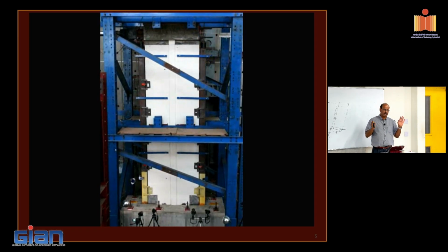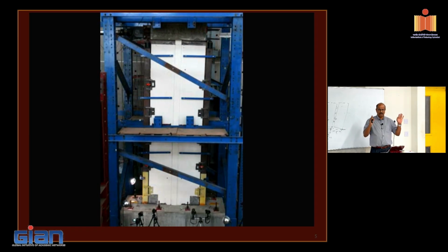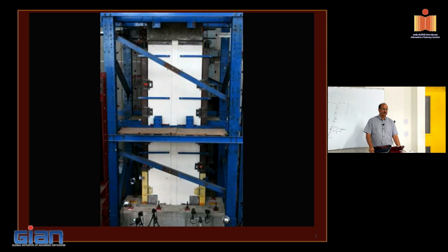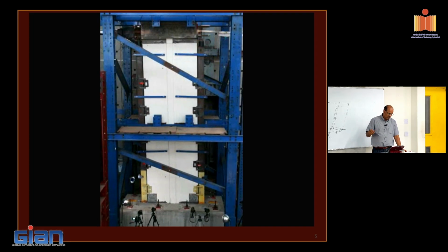This test was done quasi-statically. So it's a slow test, but we were able to quantify the behavior. So you keep pushing into the larger displacement. We designed the post-tension to remain elastic, even when they go to a large expected displacement, and the performance was pretty good. Now let me show you the next video.